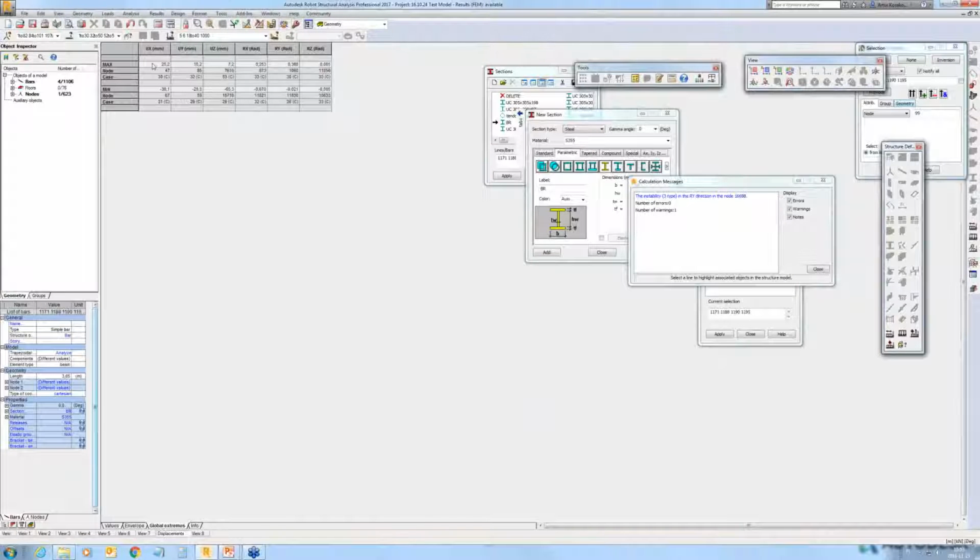That's what I wanted to achieve by defining the elastic releases, and we do not have for the horizontal UX degree of freedom this 99 millimeters of displacement for the bracings. Okay, so this looks fine, but if we have a closer look at our axis rotation, this value is still larger than I would like to see it.